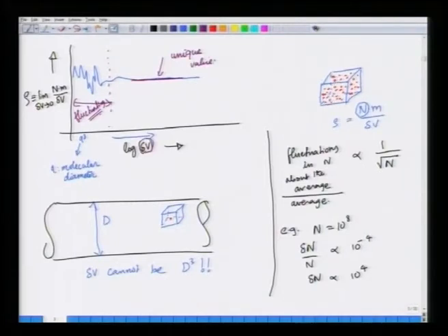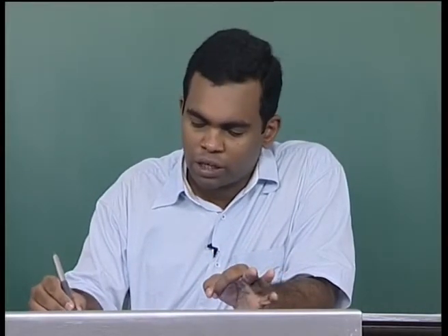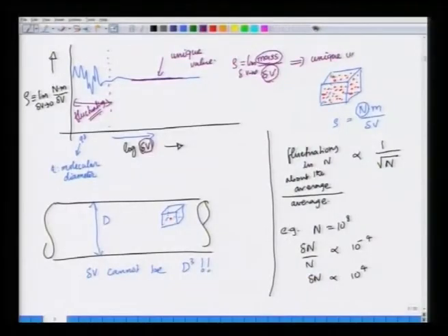That is, density is the mass present in that tiny volume divided by the volume. So, it is defined as the limit as delta V goes to 0 of mass divided by volume. As you shrink the volume such that it is still large compared to the molecular scales, the mass present in that volume will also decrease, but the ratio of these two will approach a unique value, that is the continuum density. Okay, this is the density as defined in the continuum approximation.